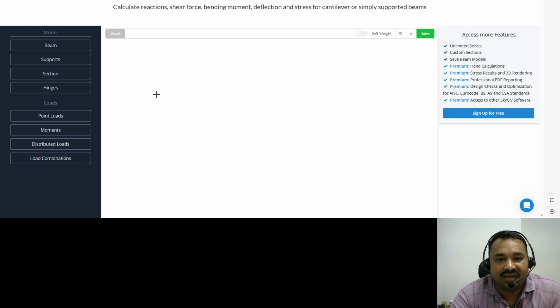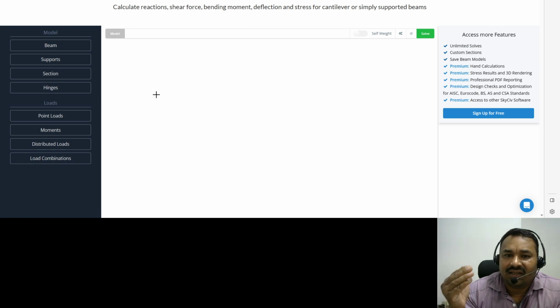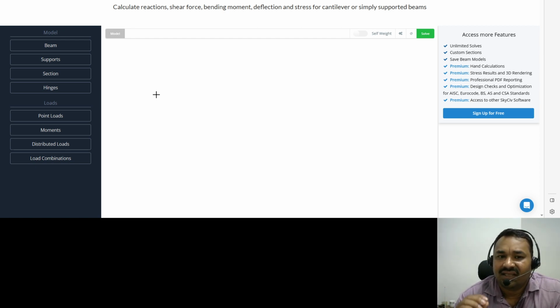And bending moment is the summation of the moments acting on the beam over the length. The shear force diagram is the variation of the shear force over the length. The bending moment diagram is the variation of the bending moment throughout the length. And here, why is shear force considered? Because the deformation occurs much more in the lateral direction rather than the axial.